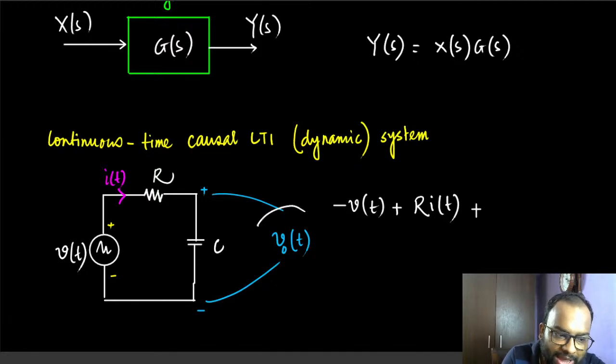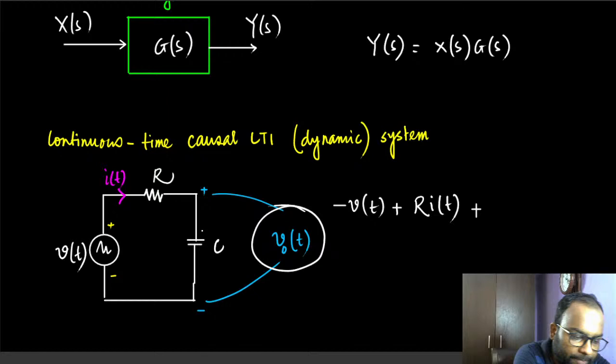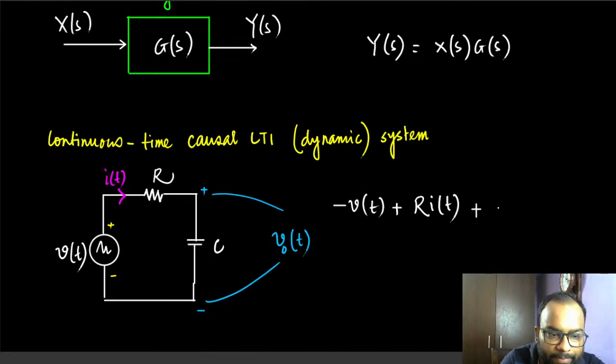We have defined it as V0t. So V0t has been defined as the potential drop across the capacitor, and then we are reaching the datum node here, the reference node here. So you're reaching the reference node here. So that way, we are ending with the equation. One loop completes, and this is the mesh equation. That's the KVL equation, Kirchhoff's voltage law equation.